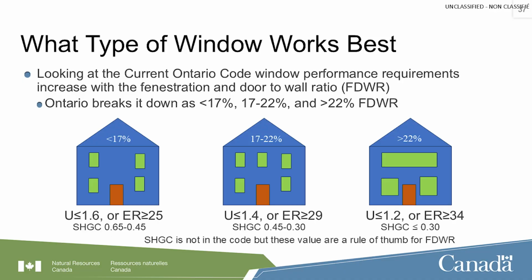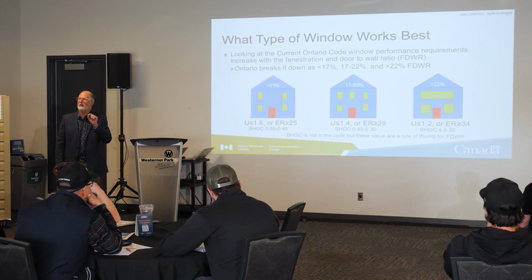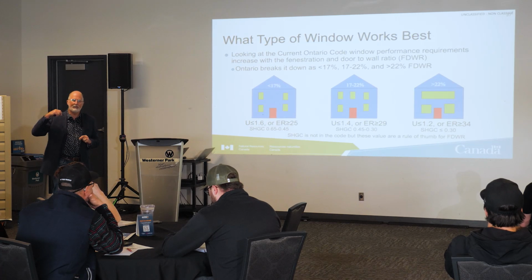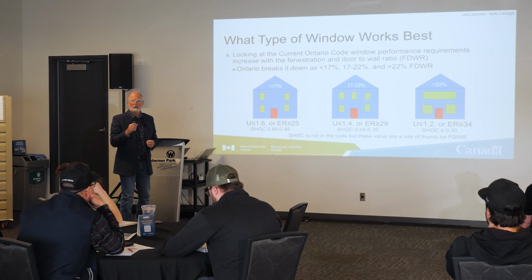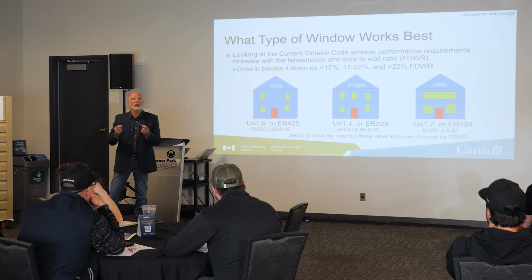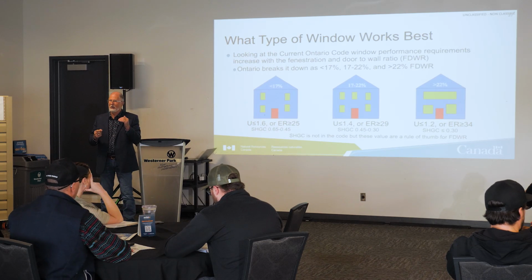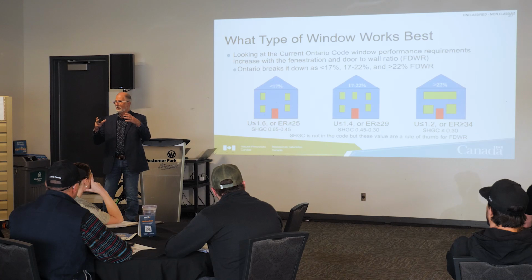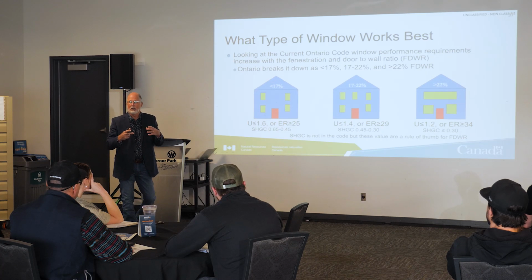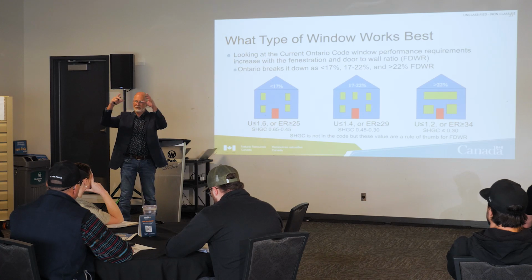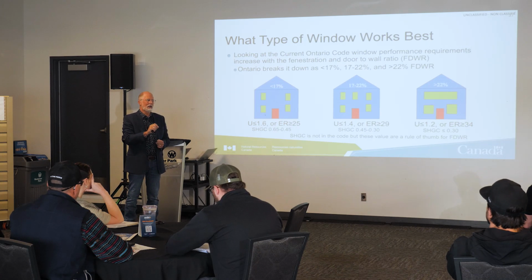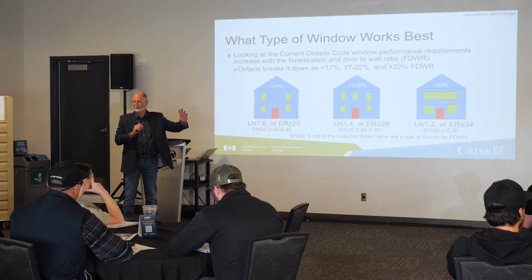And here's where it comes into the different window percentages, because this is what dictates both your free heat from the sun and your peak cooling load. Does everybody understand peak cooling load? So peak cooling load, when you do an energy model and you put the window values in, and you put the positioning of the house, and you put the environment that the house is going in, it's going to tell you how much sunlight is coming in through how much glass, through how much solar heat gain, and what's the risk of overheating that house based on a comparison to a reference model.